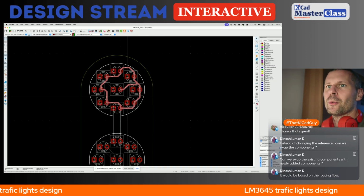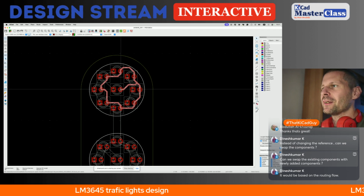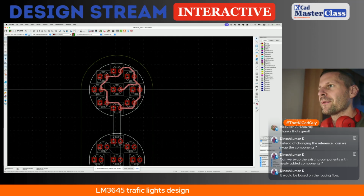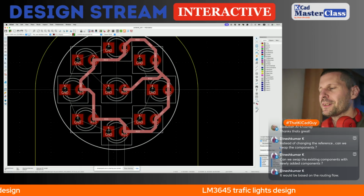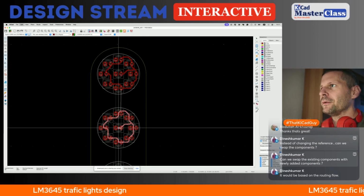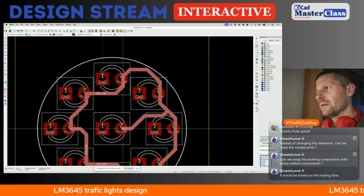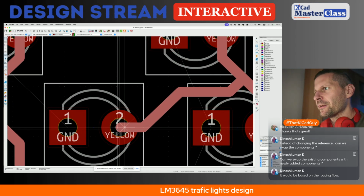Okay, now you have selected tracks. Now switch the grid to 0.5 because we place the LEDs in 0.5 grid. Now in the center of the center LED, press Control C or Command C and Command V, and let me place it. Yeah, this is the snap to graphics.